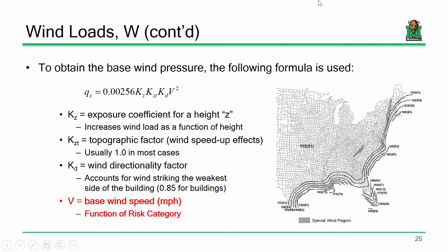I would argue that's more of a concern with seismic than with wind. When we look at seismic forces, what we're essentially doing is asking how many G's the building has to respond to. Imagine if I took Smith Hall and just picked it up and held it right there. That building would be experiencing 1 G, because it's just subjected to its own self-weight. On some earthquakes, you can easily get 2-3 G's. That's why it's much more of a concern with seismic than with wind. Yes, you can have some strong forces with wind, but nothing like seismic. Is that a fair answer?